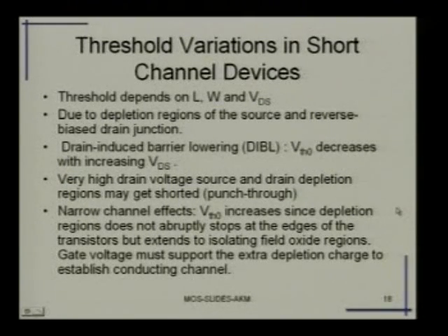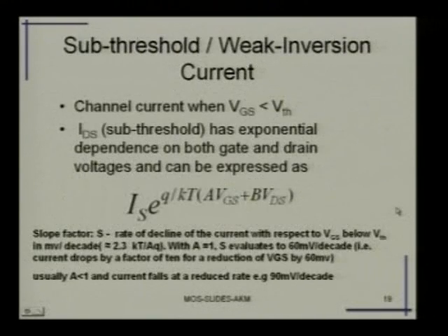That means subthreshold currents. We have said that the below-threshold current is 0, which is not the case in reality. Current will not be 0 in general. It depends on many things, particularly the gate to source voltage, and also q by kT.